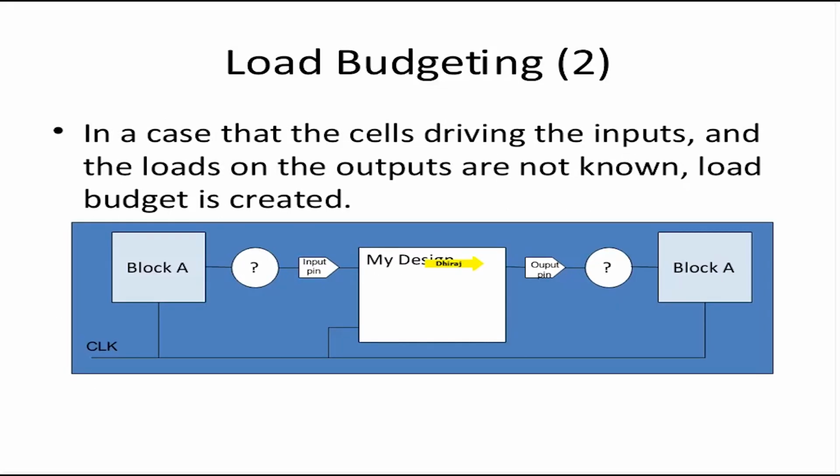So now what do these constraints do? The input constraint, input transition time, will let Design Compiler correctly calculate the delay of the logic at the input boundary. An output load will enable Design Compiler to instantiate a higher drive cell at this point. So you are safe on both the input side and the output side.